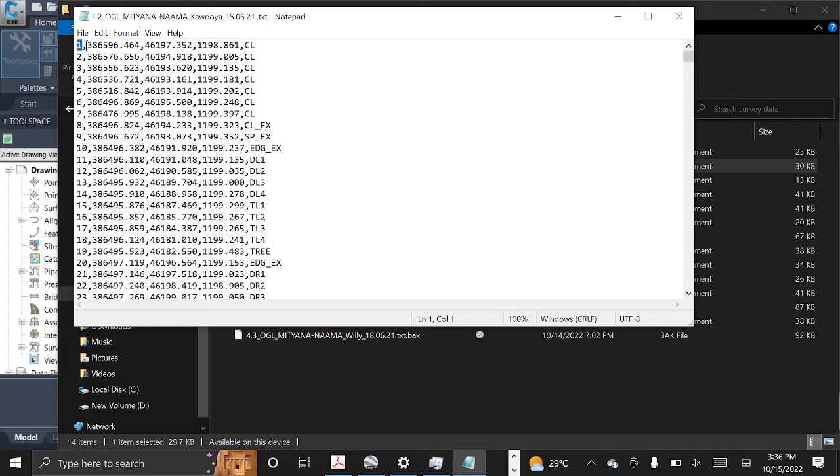As surveyors are collecting or picking these points, usually they automate the numbering. When they bring in that information, they also try to set a certain format with which they save it. For example, here you have a point number, which makes that a P. Then the next one is an easting, then the northing, then the elevation, then the point description.